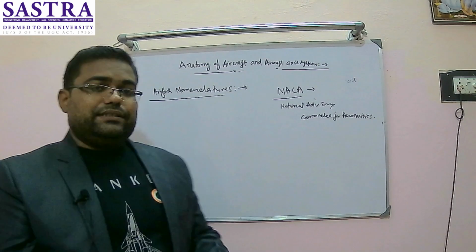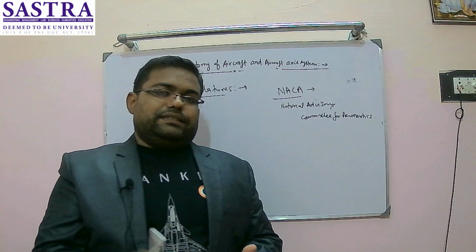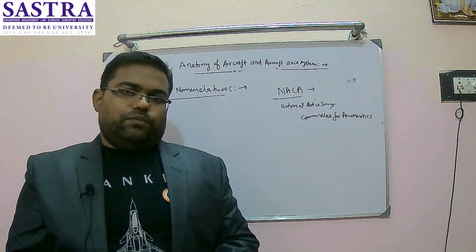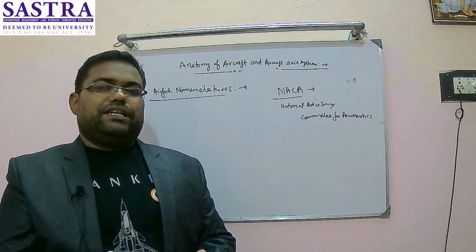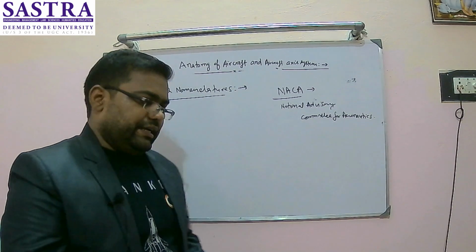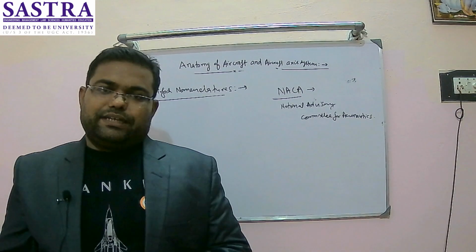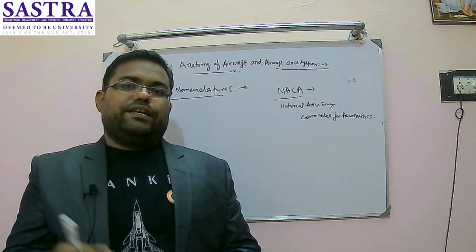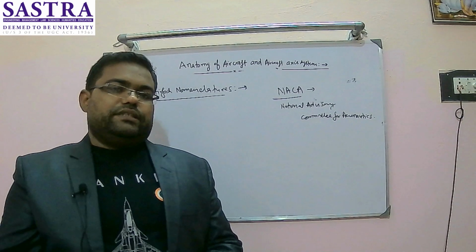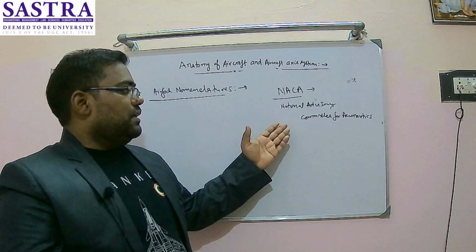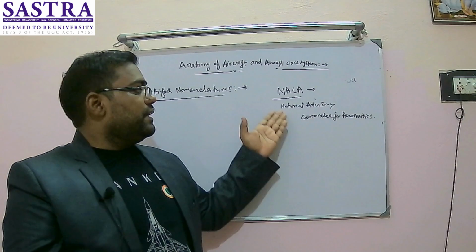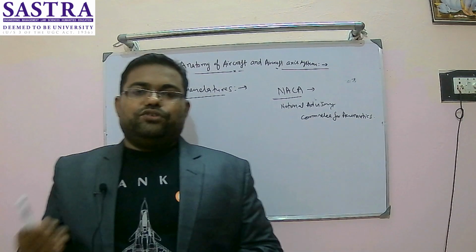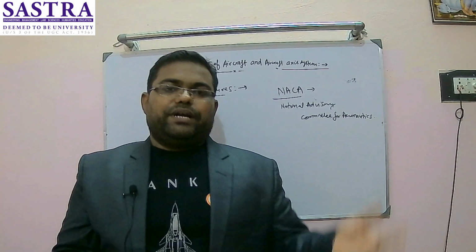They have given three series of airfoils: 4-digit, 5-digit, and 6-digit. Some of those we still use in aircraft, particularly passenger and fighter aircraft, and the 6-digit series is used in wind turbine blades. These are all designed with the help of airfoil shapes given by NACA. NACA airfoils are the standard to which any newly designed airfoil is compared.